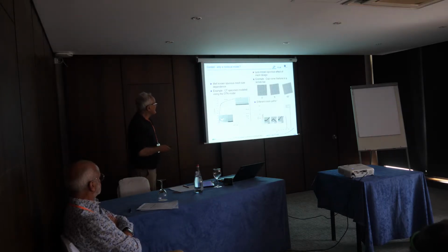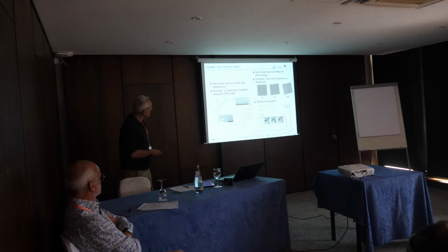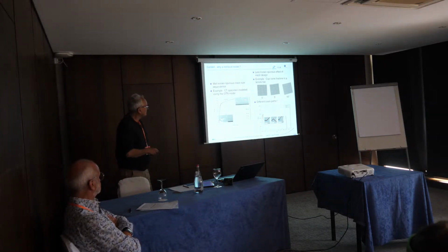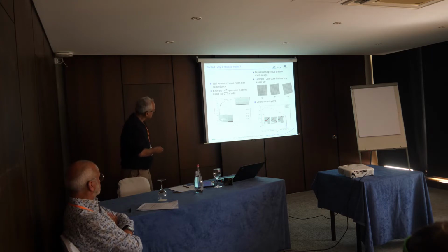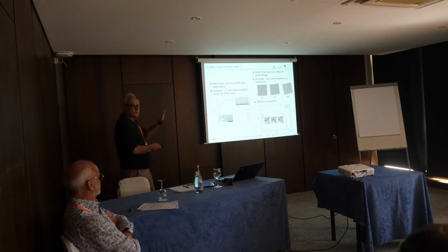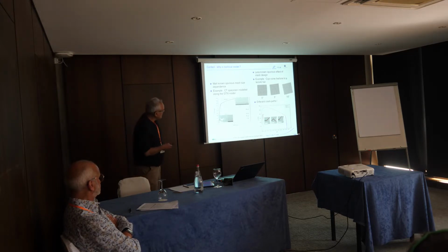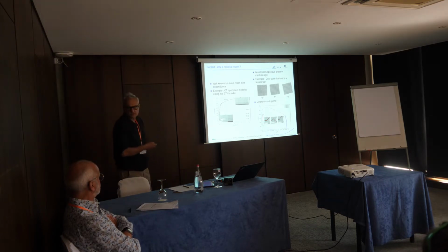Something which is maybe less known is the spurious effect of mesh design. For instance, here I'm trying to simulate cup-cone fracture, and I designed an initial mesh, which is aligned with the load axis. So it's 0 degrees here, and then I start tilting this initial mesh by 5 and 10 degrees. Indeed, there should be no influence of the mesh orientation on the results.